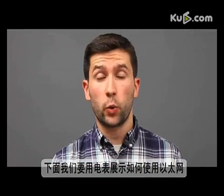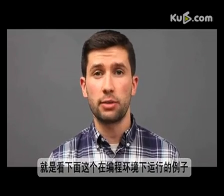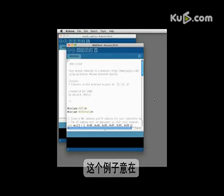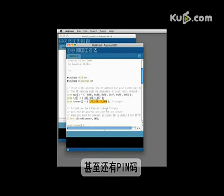So now that we have our meter working, we need to take a look at how to use the Ethernet shield. The best way to learn is by looking at the example that's included with the Arduino development environment. In Arduino, go to File, Examples, Ethernet, and choose Web Client. This example makes a search request to Google's trusty servers and returns the result in the serial monitor. You may need to adjust your own IP and even Google's server IP. You could do a ping to look those up.